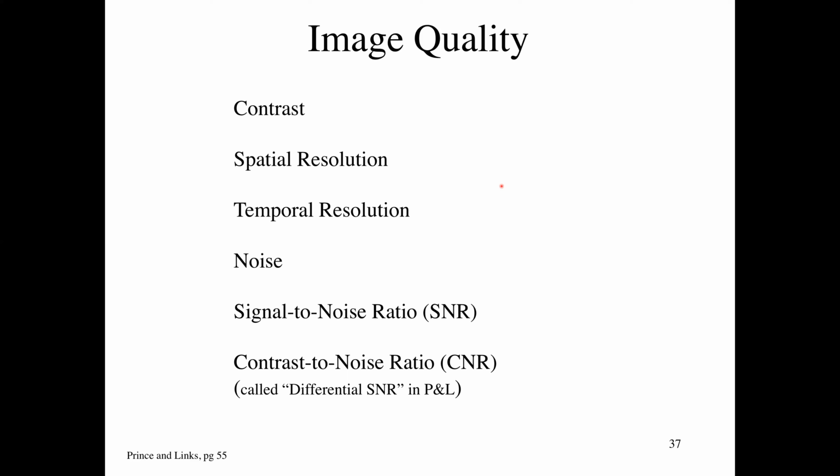That's coming from the thermal effects on the coil. When I put it up against the patient, the noise gets bigger. So the patient is a source of noise, the Brownian motion of all the things in the patient, right? And that noise is very well behaved. It's Gaussian, it's white. It means all frequencies are in there.